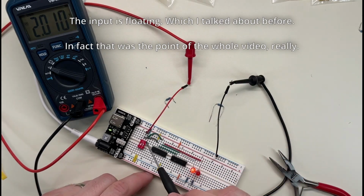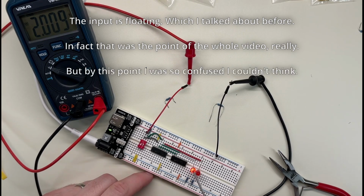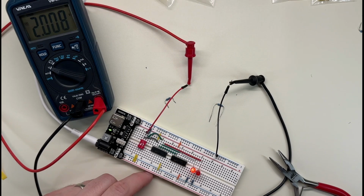So the only thing that's connected is, you know, to the gate's input here. And then that input is also connected here for the carry bit. The carry bit can only be on if both of these are on. So how are we getting 2 volts on a line that's not actually connected to anything? You know, it's not connected to plus anywhere.